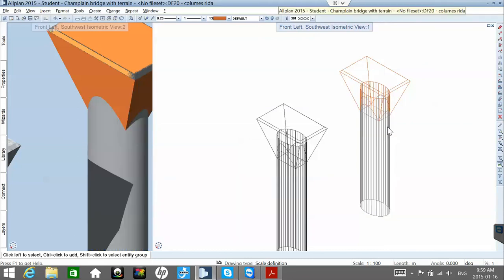Okay, so what you have to do, so vertical elements are really okay. The only thing left is what we discussed now, is to give some concrete properties to them, and create the deck as we discussed, so with constant portions and variable cross section, and then you don't need to identify points, it's way easier. Yes, yes, and you know the endings.